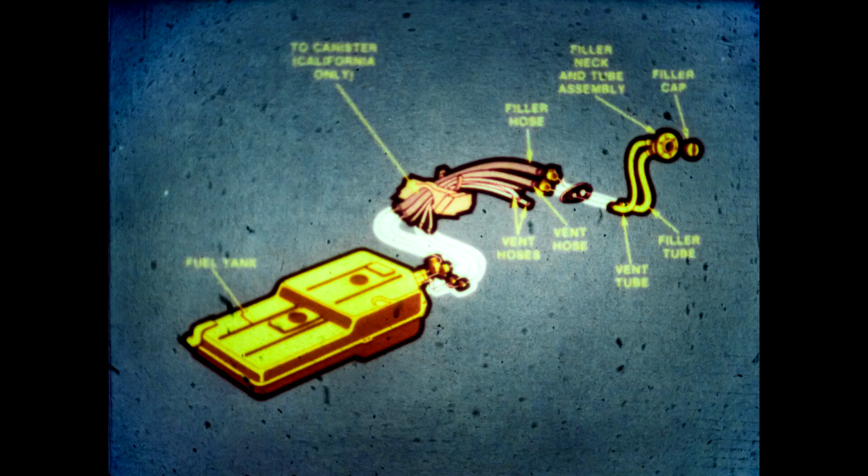The fuel tank vent lines, filler hose, vent hose, and fuel lines have added length at the rear of the vehicle to guard against lines becoming disengaged in a crash. Some filler caps have a rollover check valve to prevent fuel leaking from the tank in a rollover accident.